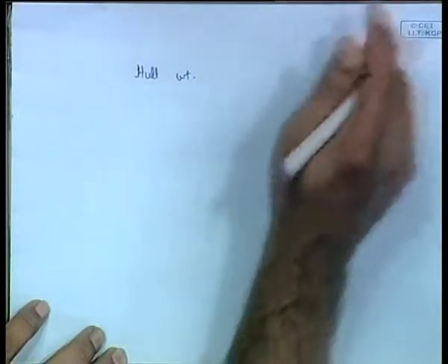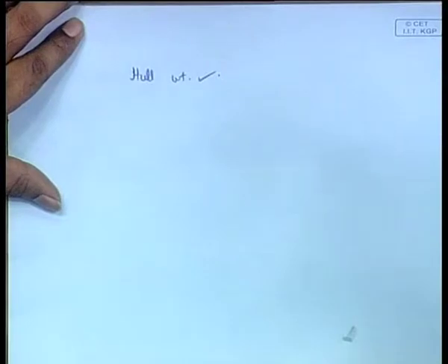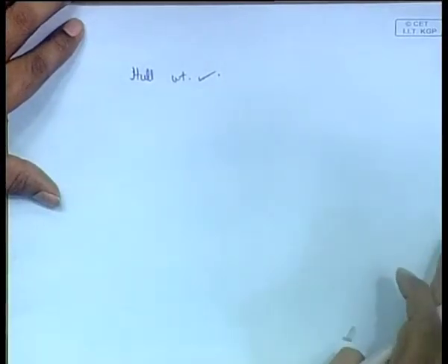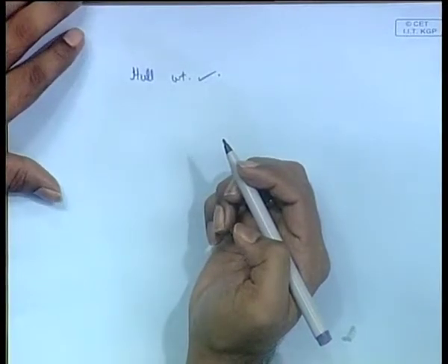First, we talk about hull weight. Hull weight in general means just the hull, nothing else but the hull. You take the ship, you have the hull, there is nothing inside the ship as such except for those structures, except for the walls, like it is an empty building. So, just the hull, that is known as the hull weight. It is mainly the weight of steel which is going to make the ship. Now, once you add propellers and some appendages to it, you have rudder, propeller, all those things, once you add that, you get some more weight, that is known as the light weight.